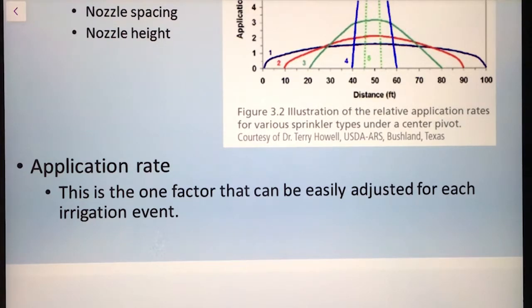So there are some things that we can do beforehand to try to maximize infiltration rate. Again, have residue out there on the surface. Maybe plant on the contour, so that residue from the previous crop is there on the contour of the field, and that will decrease the runoff of that water and allow for more infiltration.